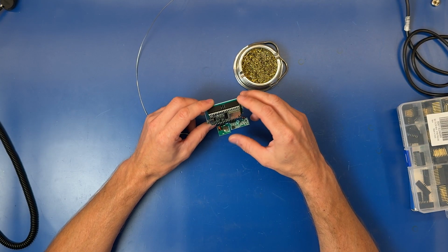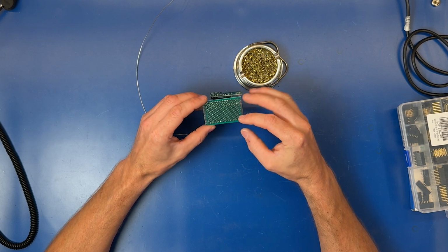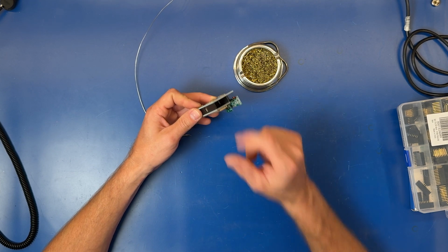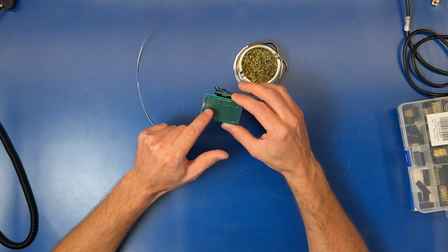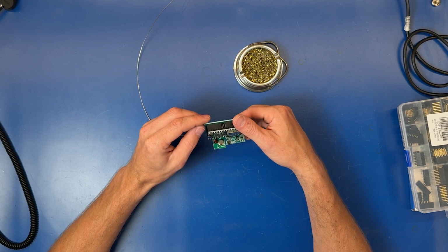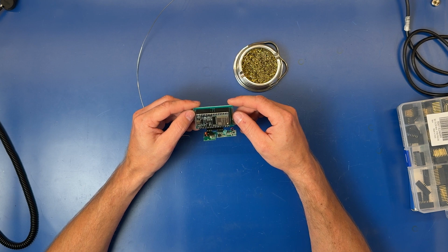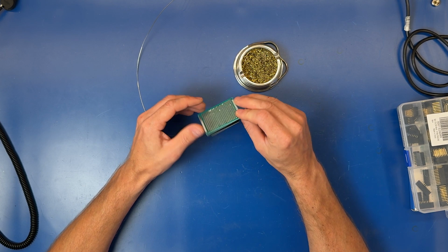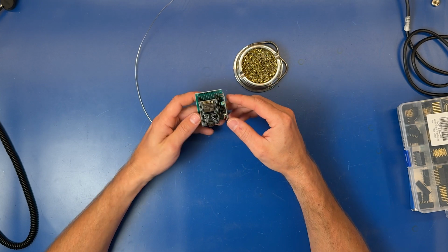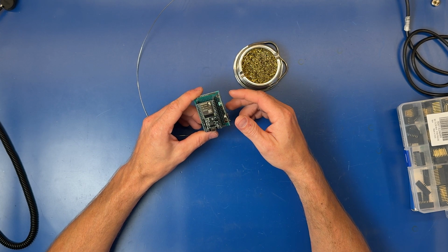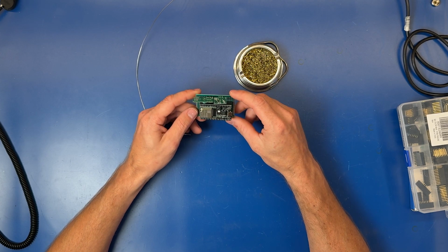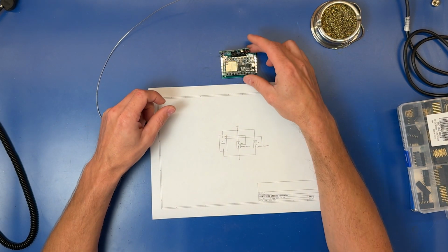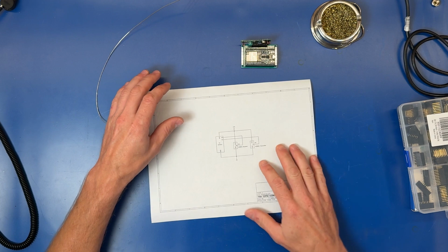So we just solder in the headers, but I didn't solder in all the pins of the ESP32 headers, and the reason is because we don't really need to. I will probably just solder the pins that we'll use, and the pins that we'll use will probably be like, I don't know, 4 or 5 pins. I know 1 or 2 of them are actually just for power, and then 2 for data.